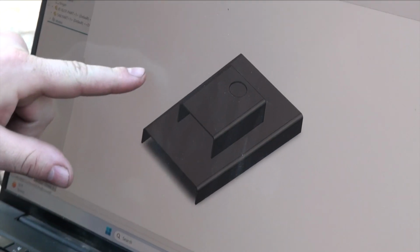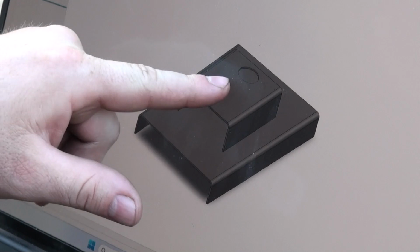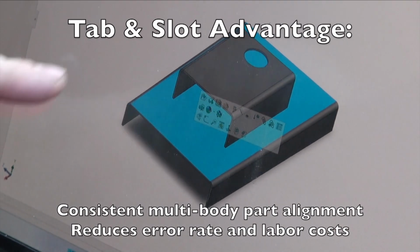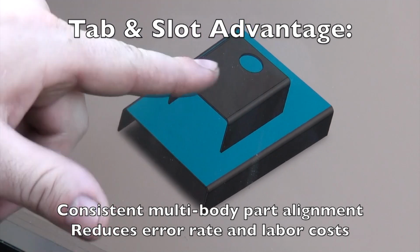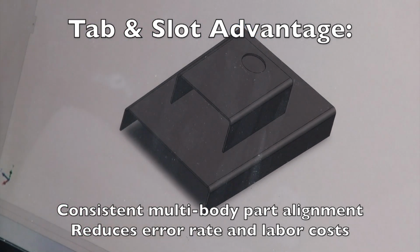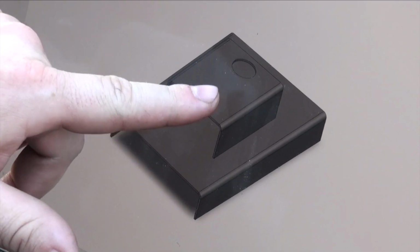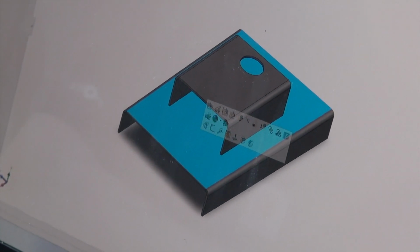So what we see here is we have two sheet metal components. We have a 14 gauge channel on top. We have a 14 gauge channel on bottom. We don't want to mess around with locating this as we're welding them together, so we want to utilize tabs and slots, which will help locate this part on top of that part consistently.